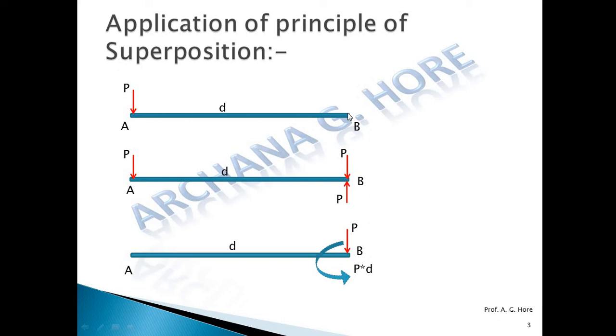Okay. Now this first diagram is known as a force system, and the last diagram is known as a force couple system because it has the force with a couple. Now in the numerical it is given to transfer that force from point A to B. So how do we transfer, and shift that force, or find a system which is the equivalent force couple system at point B. Like this the question is asked.